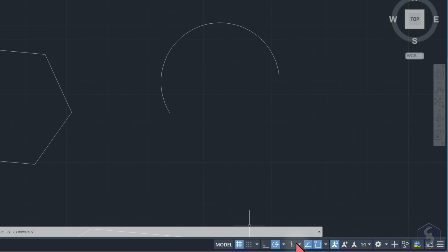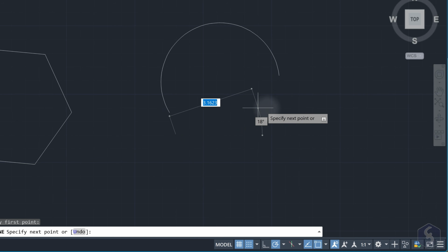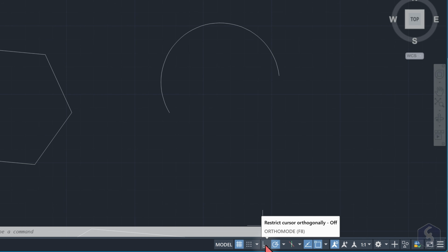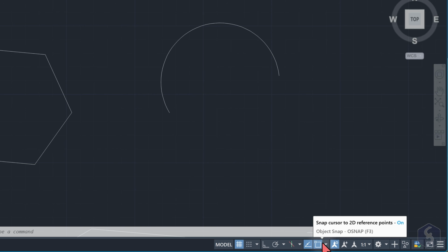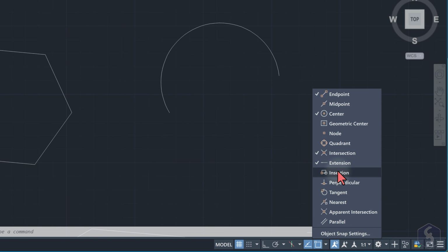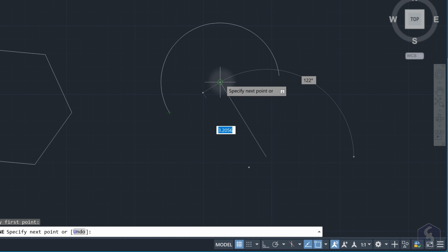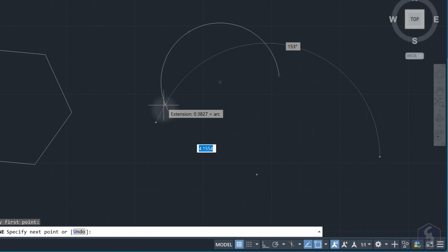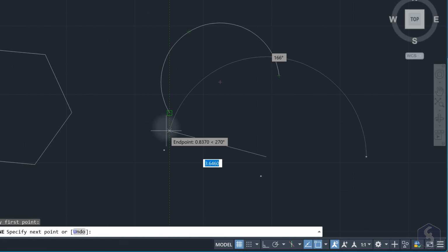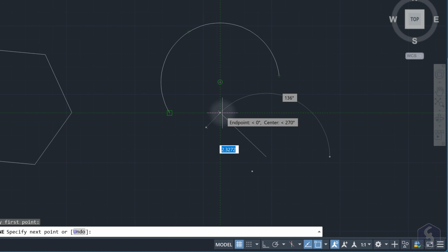You get other drawing aids from the bottom right corner. Click on Grid Mode to turn the grid on or off, on Snap Mode to toggle snapping to the grid, and Ortho Mode to draw along the X, Y, or Z axis. Enable Object Snap to snap to green key points like endpoints, centers, midpoints, and much more you can choose from the list next to the button. From these points, dashed guidelines can help to align to perpendicular or parallel directions.